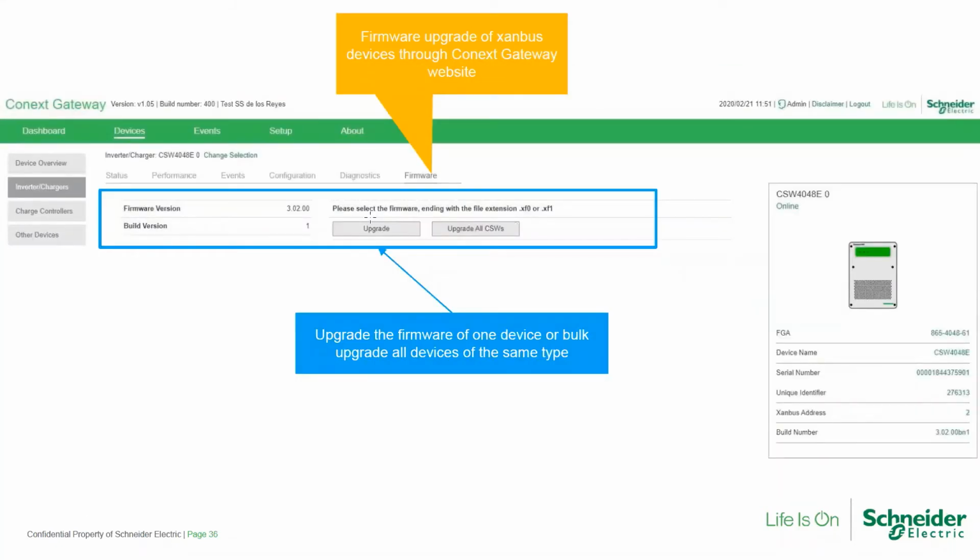Then we have a very useful tab, which is what we call, for people not very advanced on software loading, a bootloader for firmware, which means that it is able to actually load this firmware and reset the equipment at the very same time. So it's loading the operating system of the device plus the firmware at the very same time, which reduces quite a lot the problems during firmware updates, right? Typically, the problem during firmware updates is rogue pieces of software jammed inside the operating system of the equipment.